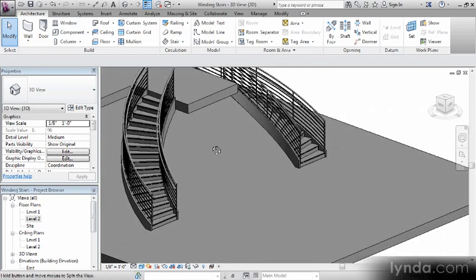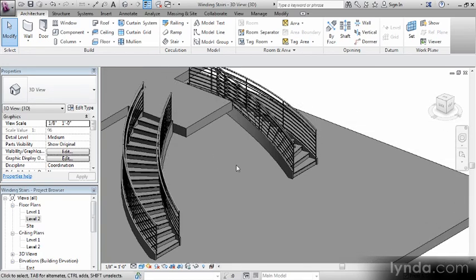Everything seems to be working out just fine. That was actually quite easy. The hard part was done. All we needed to do was first, trace the boundaries, second, trace the risers, and third, pick a railing. Always remember though, check those properties before you finish edit mode.